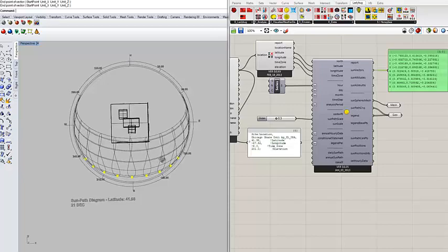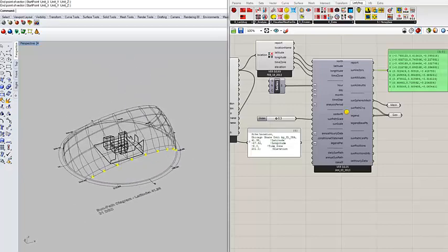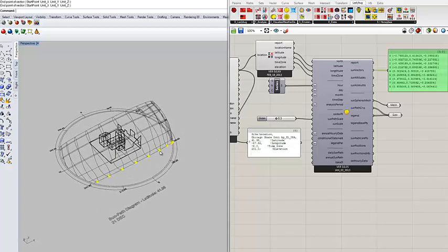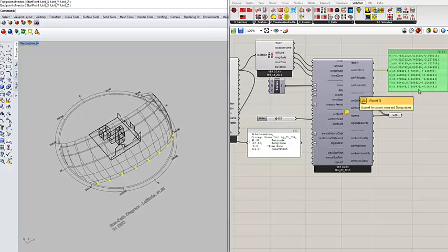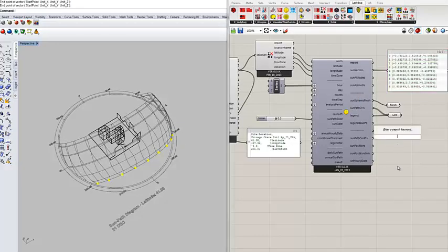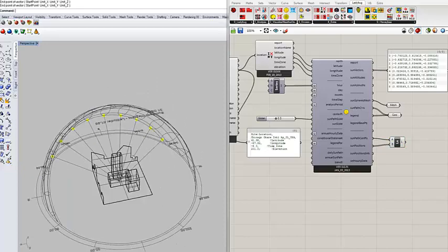And then, for example, you use that for shading design or something like that. But having this information inside Grasshopper, as soon as you have the sun, you have the vectors. And you can draw the lines if you want, for a better visualization. So I connect the center point of the sunpath to the sun positions, and it gives me these lines, which are the sun vectors.